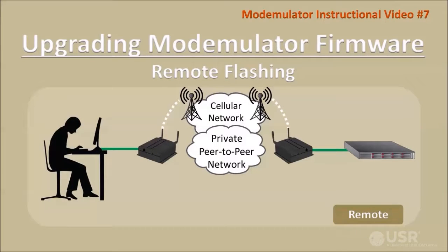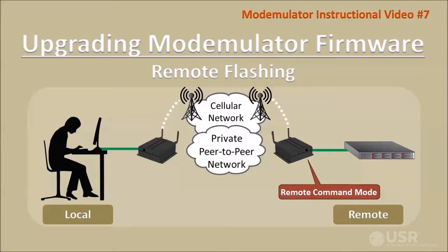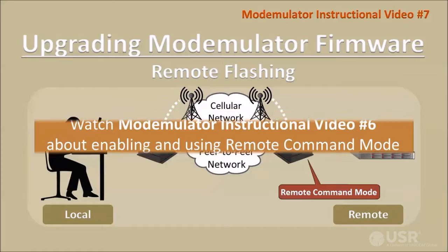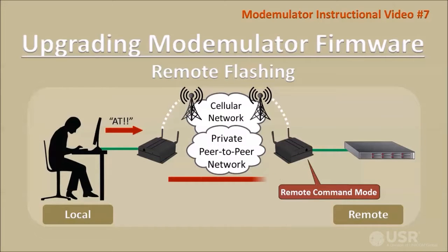The firmware of a remote Modemulator can be upgraded over the air by using a local Modemulator and a cellular connection to initiate remote command mode. Watch the Modemulator instructional video number 6 on YouTube for help using remote command mode. Once the Modemulators are connected in remote command mode, follow the same steps that are used for a local firmware upgrade as described earlier in this video.